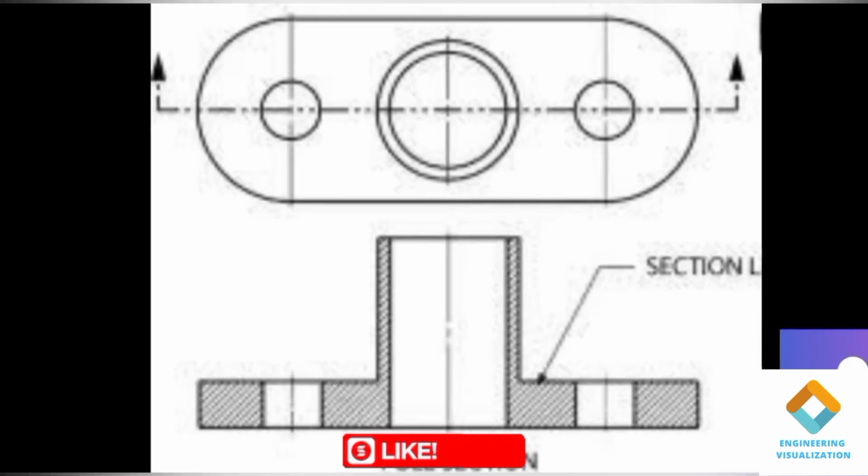The section line areas are those portions that have been in contact with the cutting plane. The exposed cut surface is then indicated by section lines. So you can clearly see it is fully cut with respect to the entire part. Hidden features behind the cutting plane are sometimes omitted unless they are required for dimensioning or for defining a part, in which case they will be shown.